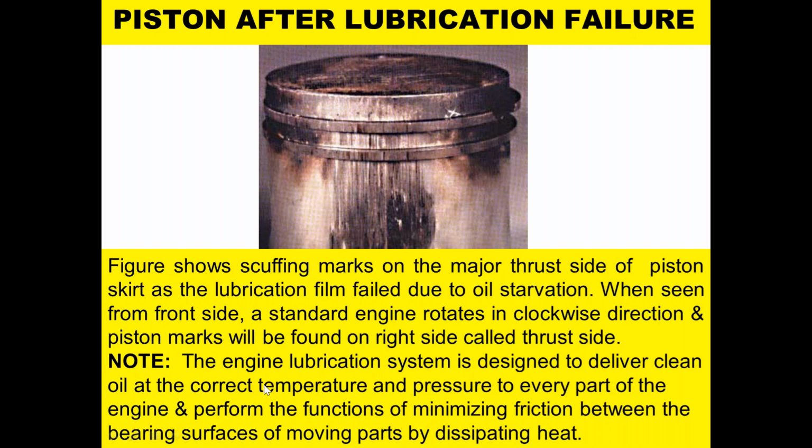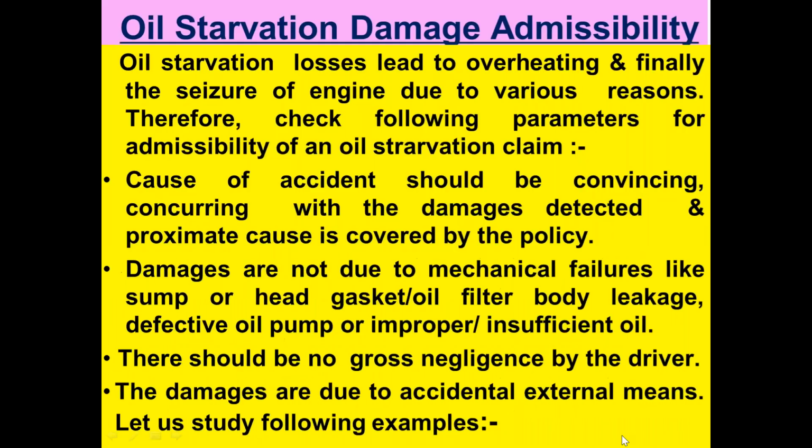Please note that the engine lubrication system is designed to deliver clean oil at the correct temperature and pressure to every part of the engine, and perform the function of minimizing friction between the bearing surfaces of moving parts by dissipating heat. Oil starvation damage admissibility. Oil starvation losses lead to overheating, and finally the seizure of engine due to various reasons. Therefore, check the following parameters for admissibility of an oil starvation claim.